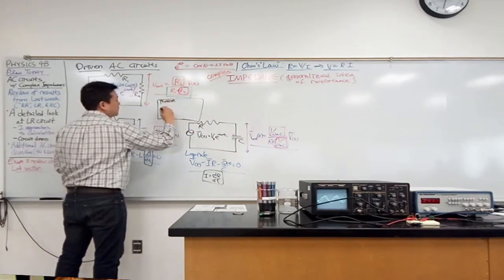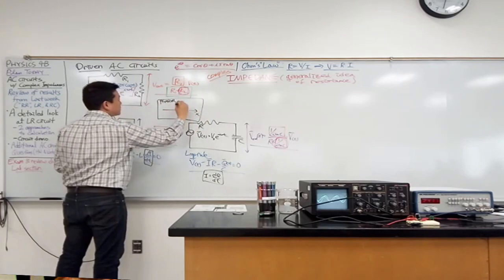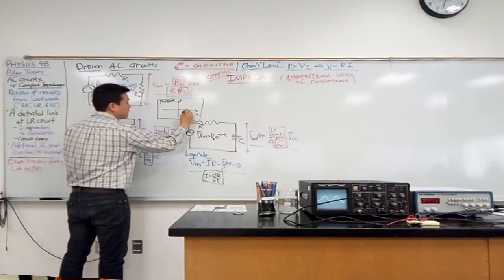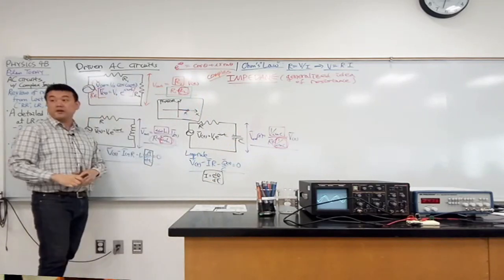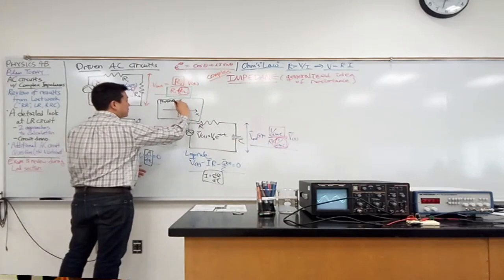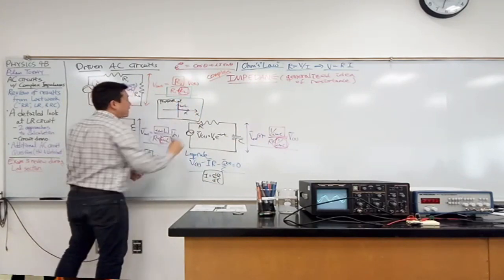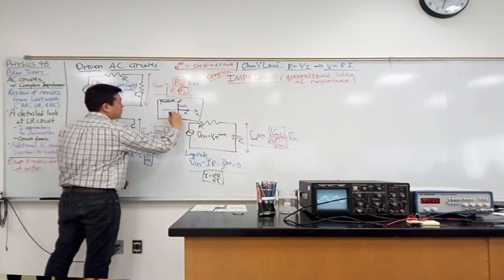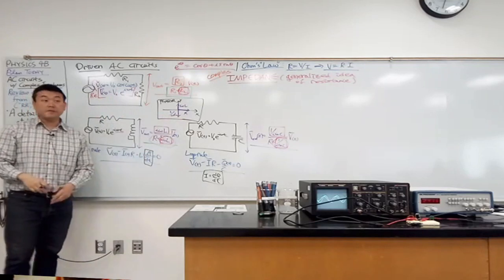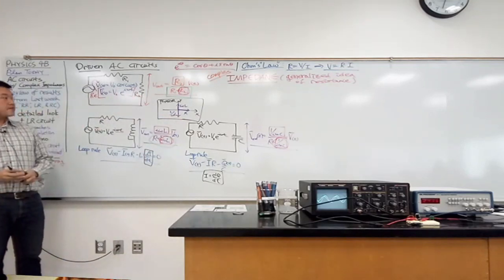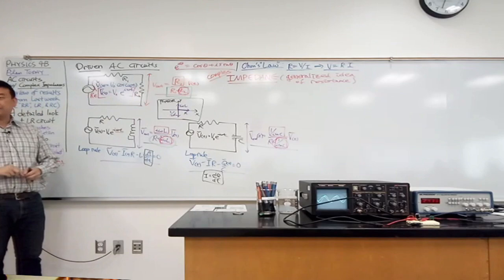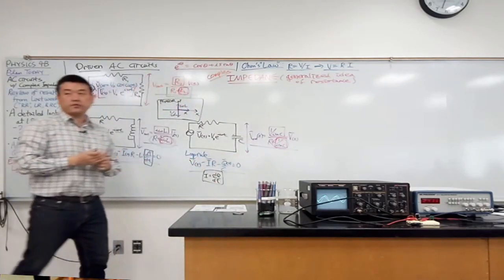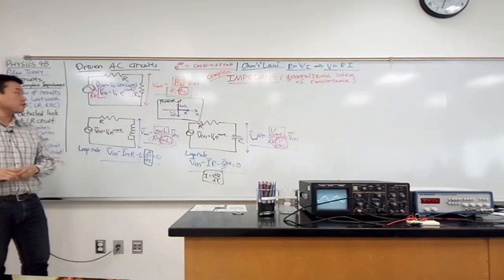The impedance phasor will look something like this: you have x and y axes, and they will tell you that impedance for a resistor looks something like this. This is the impedance for a resistor. Impedance for an inductor looks something like this with the length ωL. And impedance for a capacitor looks something like this with the length 1 over ωC. I mean, you can do it that way. But as I was trying to say as we were rushing through last time, all of this is really a very contrived way to describe something that is naturally described as a complex number.